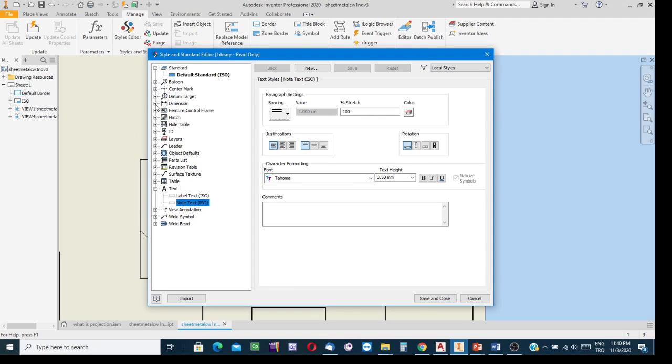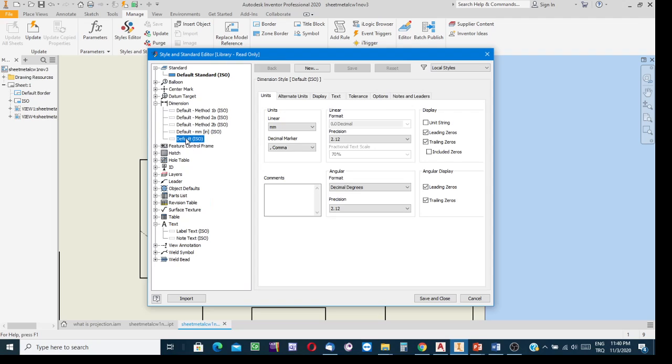And then select the dimension option, expand the list, and then the default ISO option. Precision showing the nominal values is to be in this order, 0. Well, one of the video records in the content of this week is all to make a review on dimensions, dimensioning format. You can understand why I selected 0 precision at that stage. Clicked on save button, and then display option.